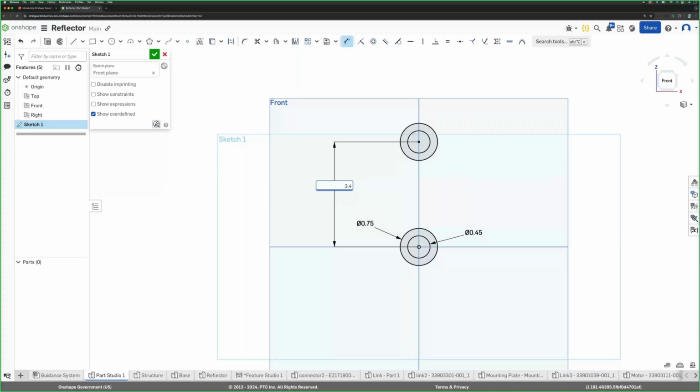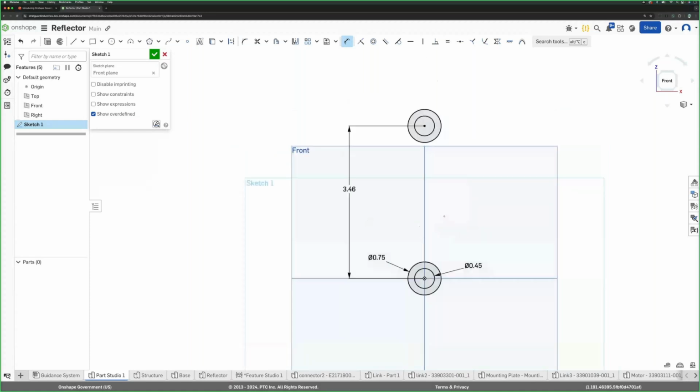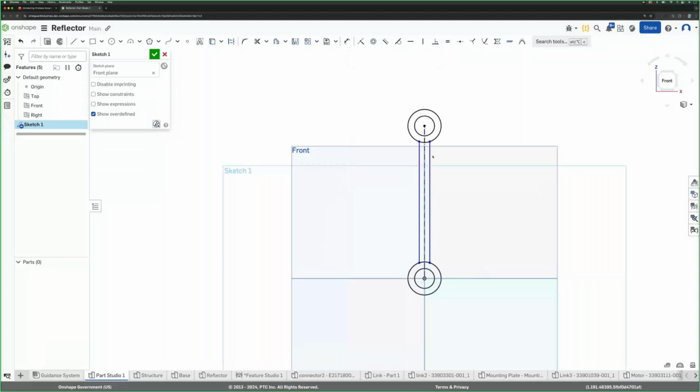First off, as I go to define the geometry here, I'm just going to create a series of lines. Notice that as I'm mirroring my geometry about the construction line, let's do a mirror. Select the geometry, I automatically get that symmetric behavior that you'd expect out of your sketch. Add a dimension to define the width, and we have our first basic sketch.